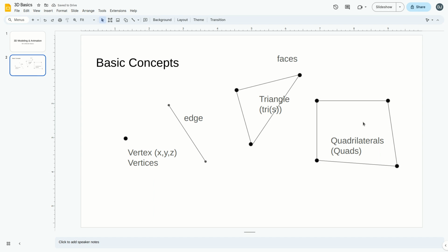This class is designed to teach people how to make 3D models that will ultimately be used for video games, virtual reality, simulation, live application. And most live applications will require your geometry data to be stored in triangles. Just something to keep aware of. Tris and quads are both considered faces. They do get rendered. But certain math works better in quadrilaterals, which is why we generally work in quads and then export in triangles. All right, so this is our basic vocabulary.